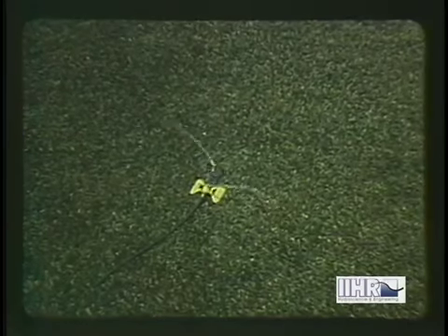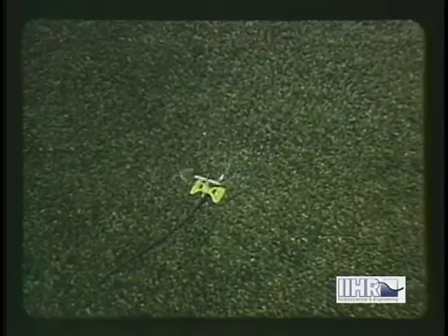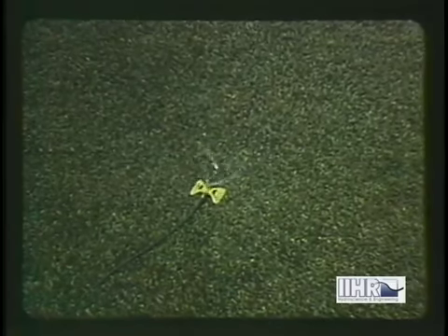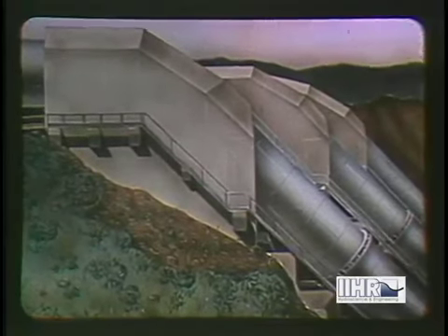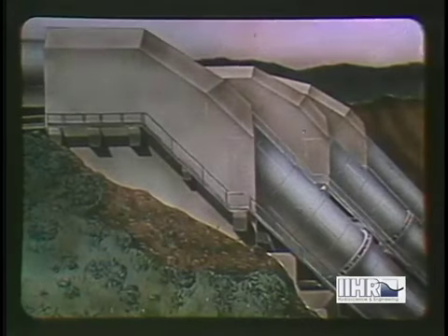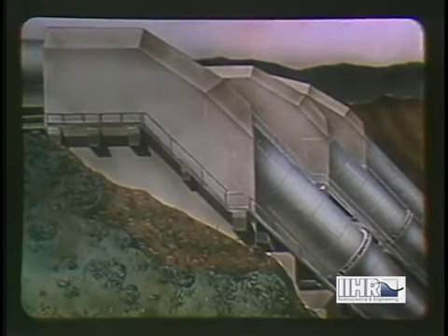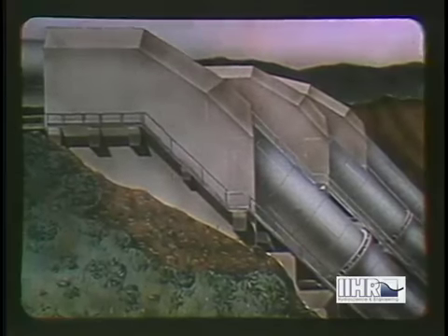The force required to modify the speed or direction of a flowing fluid has been used in one way or another for many centuries. The common lawn sprinkler is the modern counterpart of an ancient Greek steam toy. To prevent a similar movement of hydroelectric penstocks, the forces at the bends must be absorbed by tremendous concrete anchors. If such forces are not statically counterbalanced, as in the sprinkler or this runaway balloon, then a useful means of propulsion is at hand.